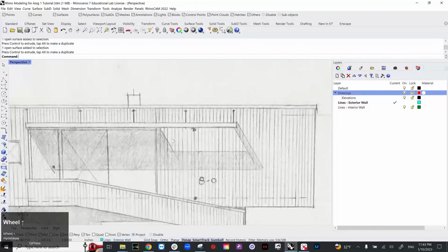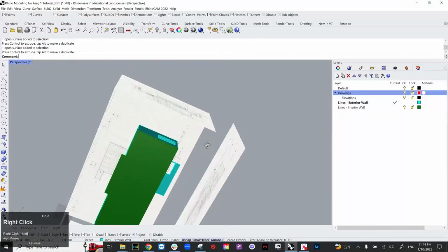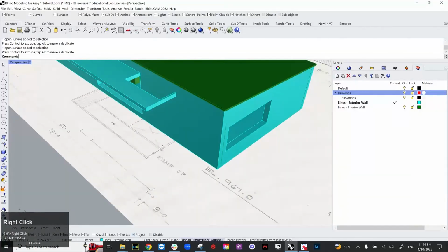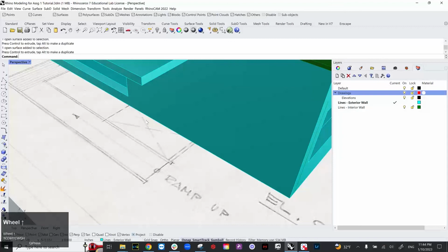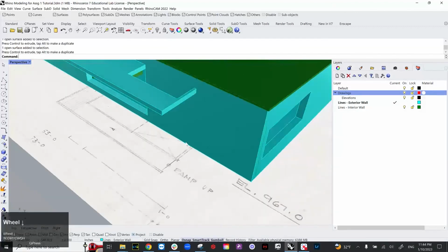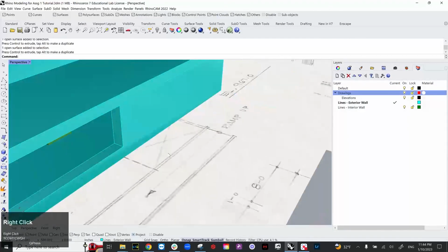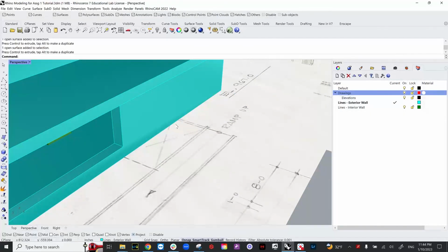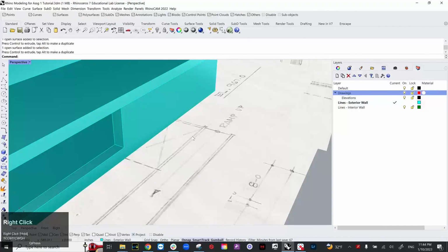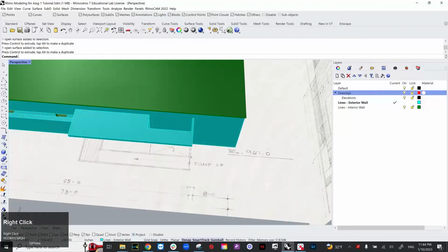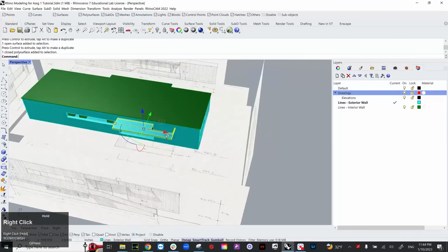But as you can see in the shadow over here, there is a shadow kind of doing this, which means there is an opening in the surface of this canopy, which is also corroborated by this dash line on the floor plan. If you remember, a dash line with the X means there is something above, or openings above. So that's what I have over here.